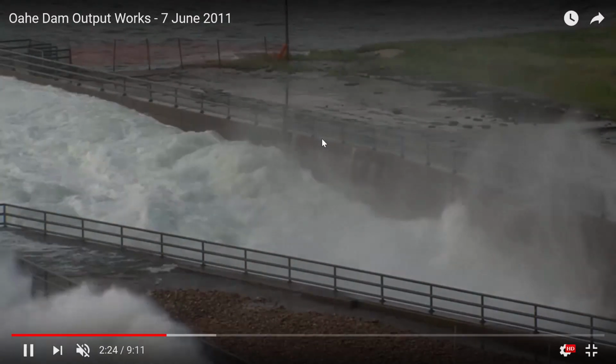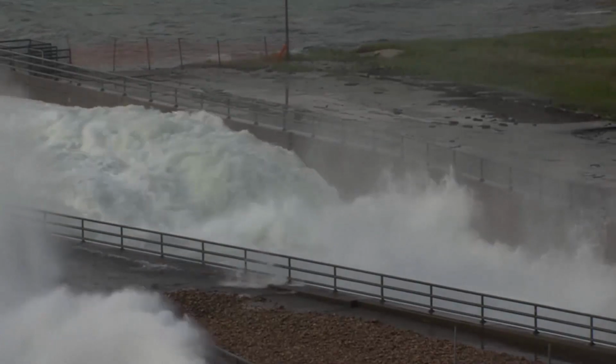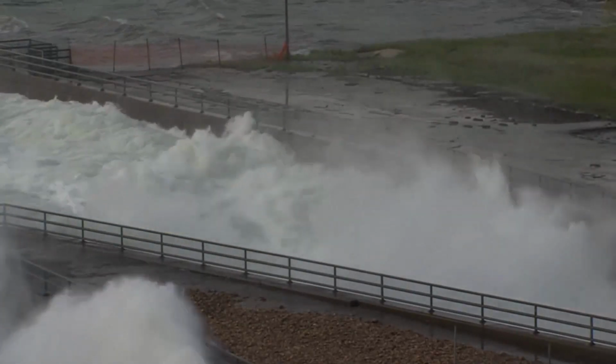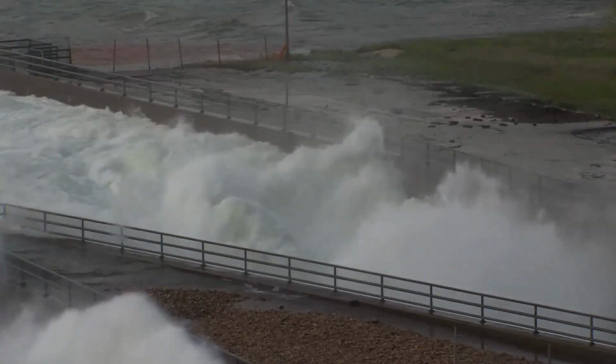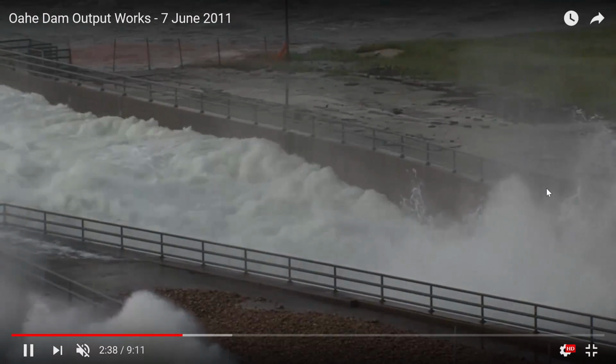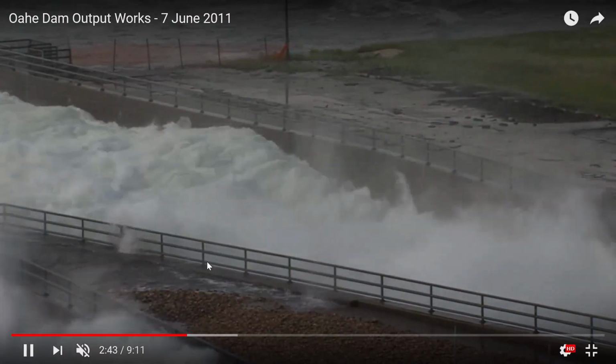So instead of allowing that high energy water to discharge right into the river where it could scour the streambed and damage the fish, or allow it to discharge really close to the dam itself, which then threatens that, they have this heavily armored concrete stilling basin where they're inducing hydraulic jumps.